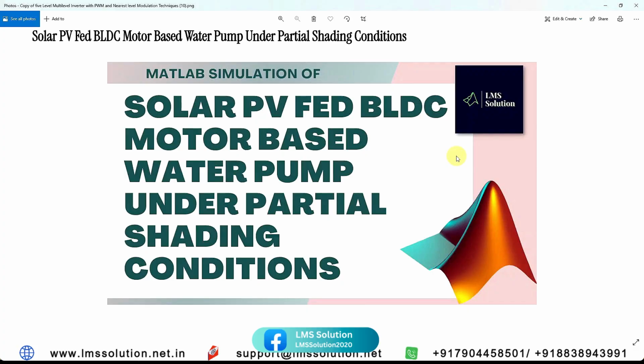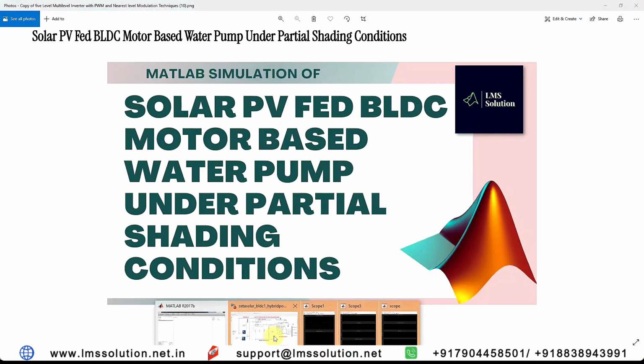Today we are going to see the solar PV fed BLDC motor based water pump under partial shading condition. I am going to explain the solar PV fed BLDC motor along with the hybrid PO-PSO MPPT. Here we are going to create a partial shading condition for the solar PV system. We want to test the system under two conditions: one is uniform irradiation, and the other is non-uniform, that is, partial shading condition. We also test the system with the hybrid PSO MPPT and the PO MPPT for the same conditions. Right now I am going to the simulation model.